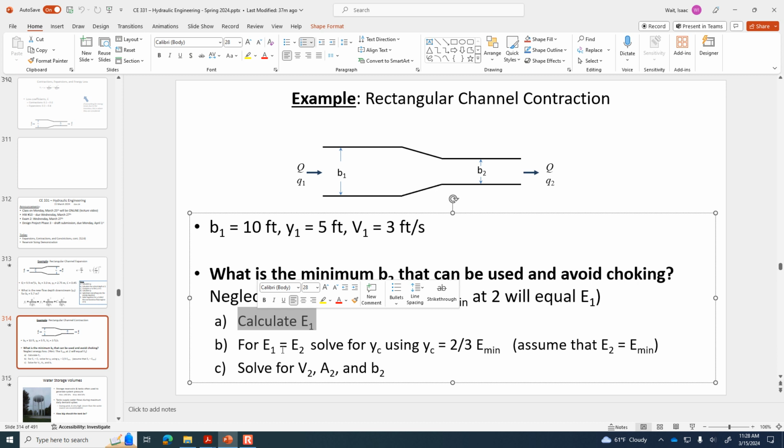So think about flow per unit width. If we make B really narrow, that's increasing the flow per unit width. So we want to know what's the narrowest B that can be tolerated. Another way to phrase that is not how narrow can B be, but what's the largest flow per unit width that we could have with the amount of specific energy that's available at 1.